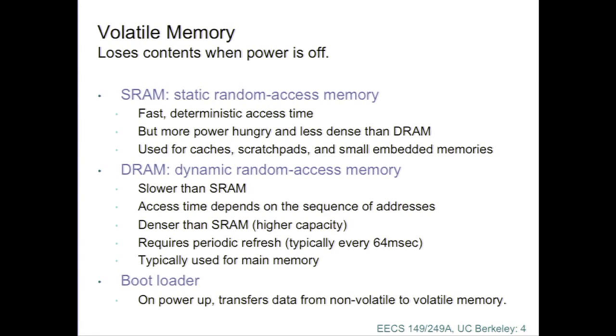Okay, so the memories are very carefully designed. There's a lot of parallelism in them. So there's a bunch of separate memories. If you read from this one, and then in the next cycle read from this one, and then in the next cycle read from this one, then things will go pretty fast. But if you read from this one, and then in the next cycle try to read from the same one, that second read is going to stall. And it's going to stall until the first read completes, which can actually be quite a few cycles, many cycles.